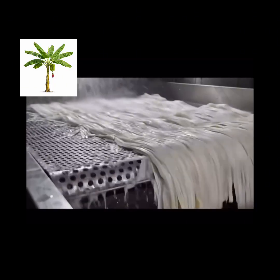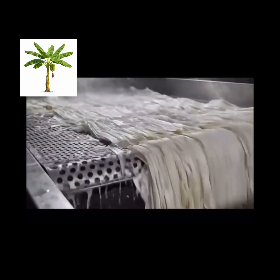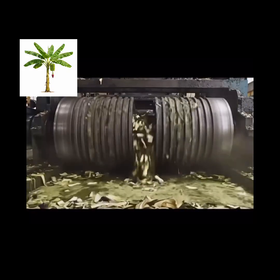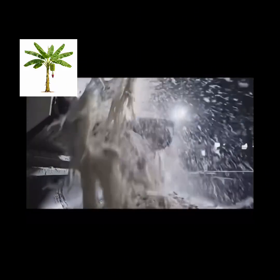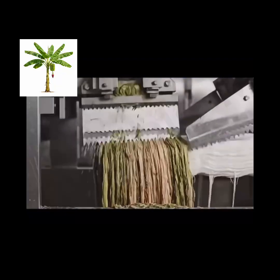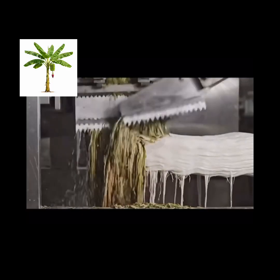In 2026, many facilities prefer enzymatic methods because they are more environmentally friendly and produce high-quality fiber. Now, after degumming, fibers are thoroughly rinsed and neutralized. They are then dried in controlled conditions. For drying, they use drying tunnels to regulate temperature and airflow to prevent brittleness and uneven moisture content.